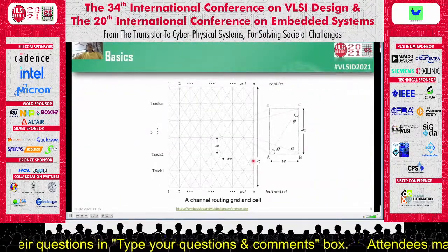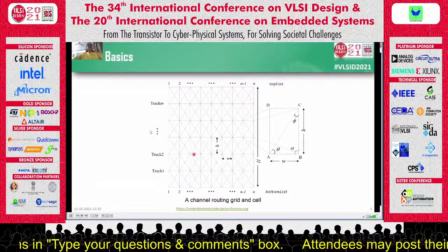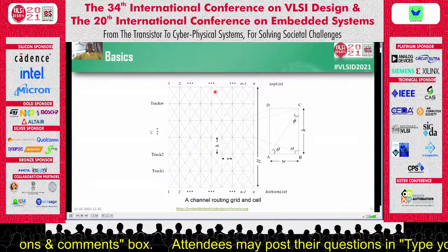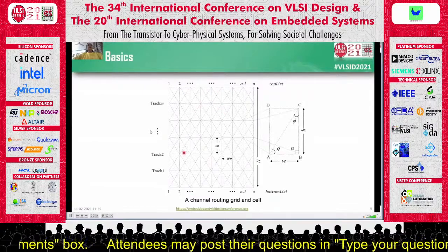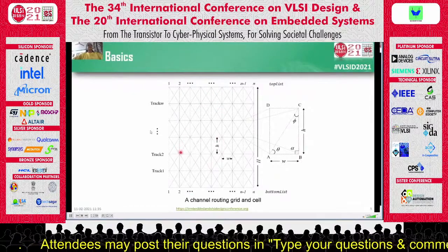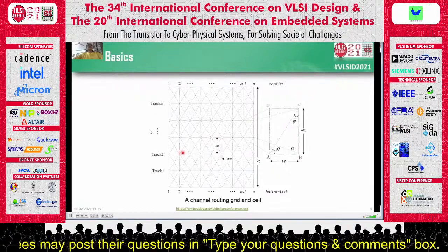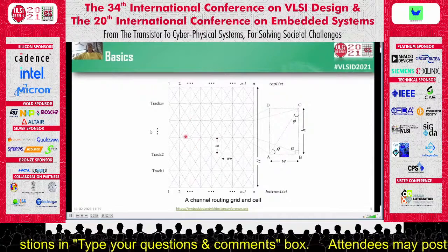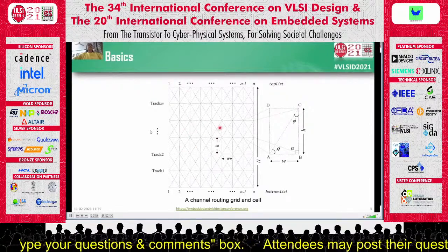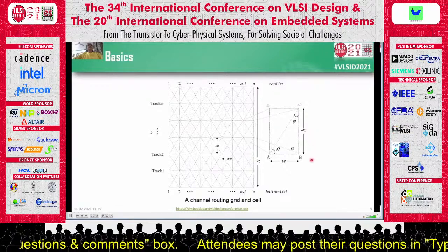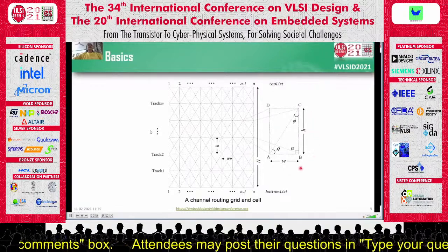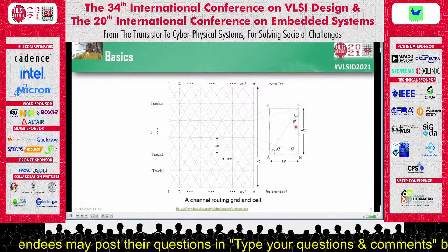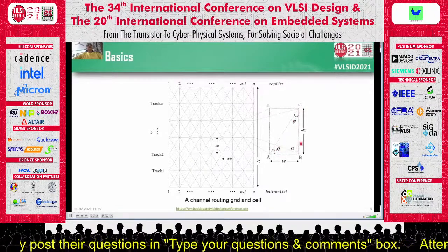In channel routing, a channel is represented as a horizontal path with the terminal list at the bottom and the top of its boundary. Here is the representation of our channel grid, where the waveguide follows a non-Manhattan channel routing, and further the grid is divided into a number of cells, where a cell is represented here. It has a height of h and a width of w, and theta, alpha and phi are the angles along the cell.